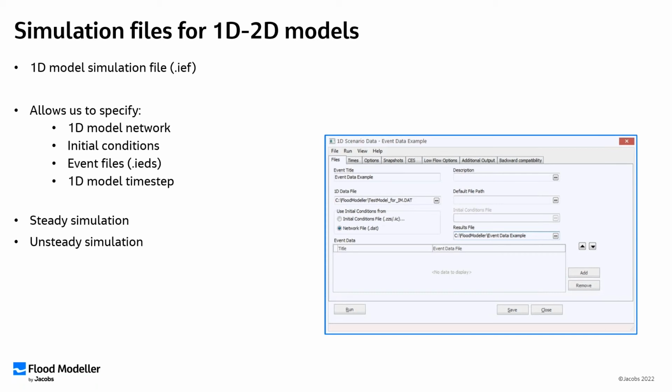We have the ability to run several types of simulations within Fluid Modeler. The steady state solver provides both direct steady state and pseudo time stepping methods to optimize runtime and enhance model stability. It is most often used to obtain an estimate of the initial conditions for your model. However, there are specific situations where steady state simulations alone are appropriate for obtaining model results.